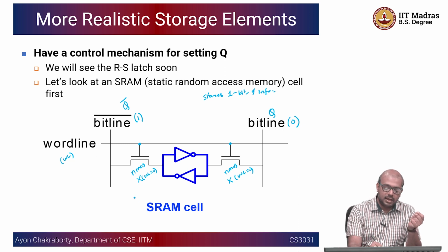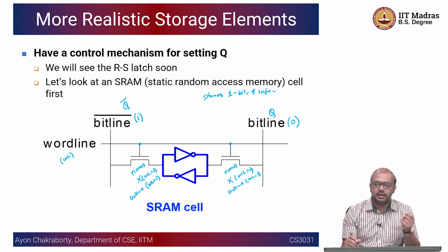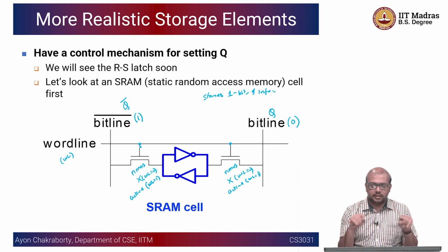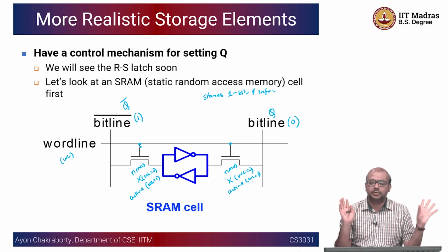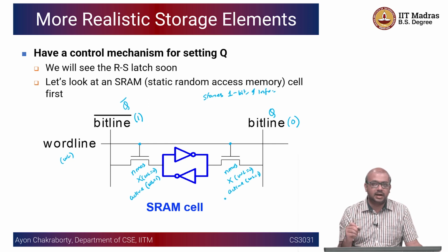So in that case, if I want to make it active, WL is equal to 1. Same here, active WL is equal to 1. If WL is equal to 1, these transistors are going to act as a closed gate, right? The circuit is going to be complete, current can flow and so on. So basically then the SRAM is going to be affected by the bit line.